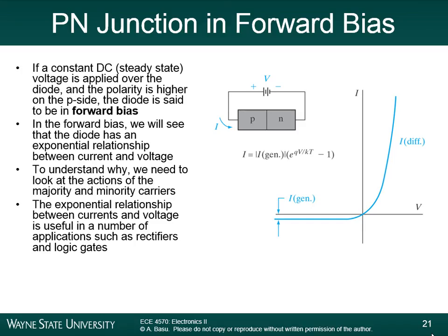They're also used nowadays in electrostatic discharge devices. Some of you, if you've done electronics lab, have probably run into this problem where you burn out a chip by touching your finger to it because your finger has a lot of charge built up. Well, there are electrostatic discharge protection circuits that use diodes. When you have a lot of positive or negative charge on your finger and that deposits itself into the device, the diodes will actually carry away that charge from the circuit to prevent it from burning out.